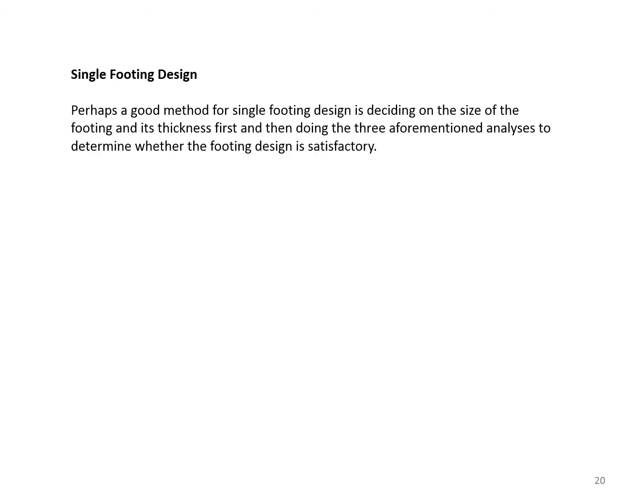Let's concentrate on single footing design. Perhaps a good method for a single footing design is deciding on the size of the footing and its thickness first, and then doing the three aforementioned analyses to determine whether the footing design is satisfactory.